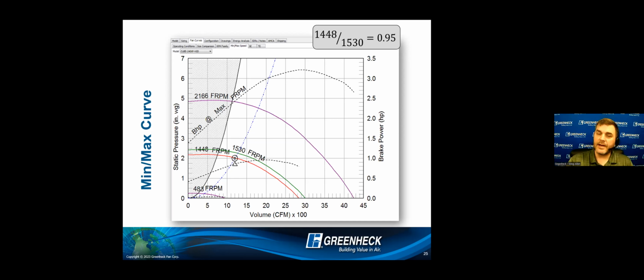Well, you're in the driver's seat now. You want to bump that motor horsepower up so that you have that higher buffer at the top end. Or you may choose to just pick a different fan where the operating condition gives you a more favorable turn up, turn down relationship. And actually, that's my next curve.